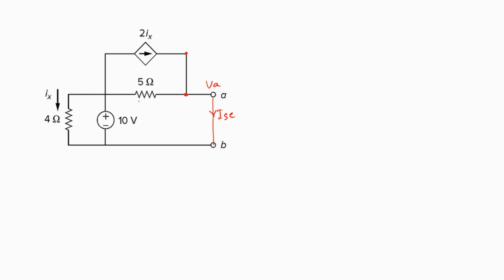So therefore, you can see that the 10 volts and the 4 ohms are connected over here, which is nothing but point B, which is nothing but point A, which is nothing but, I'll call this as B dash, A dash, B dash. So in this case, A dash is B dash is A, which is B. If I call this as C dash, which is nothing but C and C dash. So all of these points are actually one and the same. That is because there are no other extra elements connected in these wires.